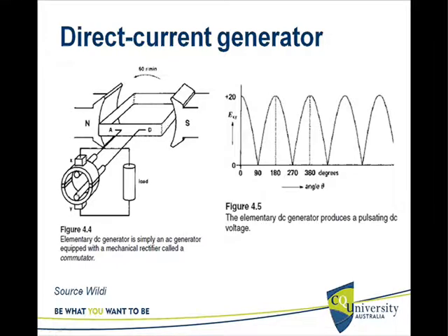this is the plane. If you consider this vertical plane, that's important. The two brushes are now in a vertical plane, and when this winding is aligned with that vertical plane, as you can imagine, which is when this winding is vertical, there is no voltage induced in the winding, because for a slight movement from that vertical position, the conductors are not intercepting any of the flux lines.